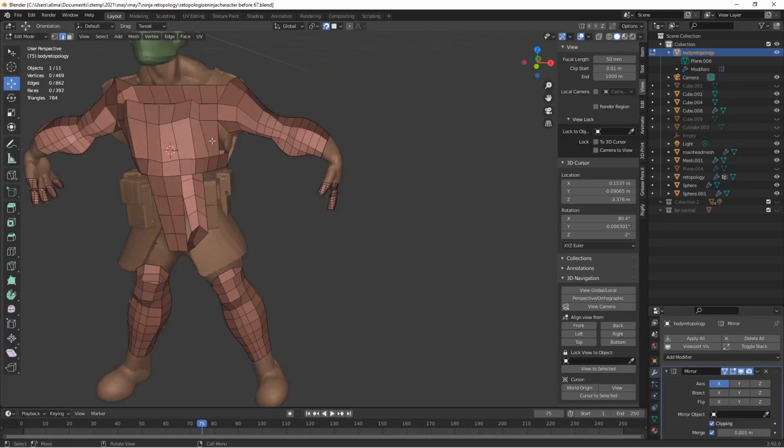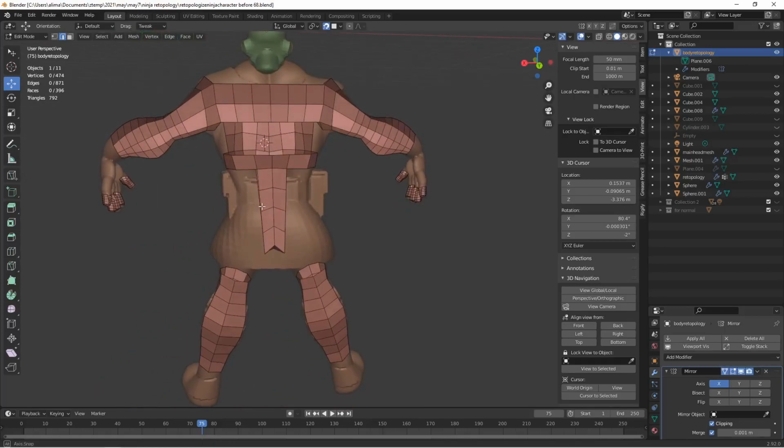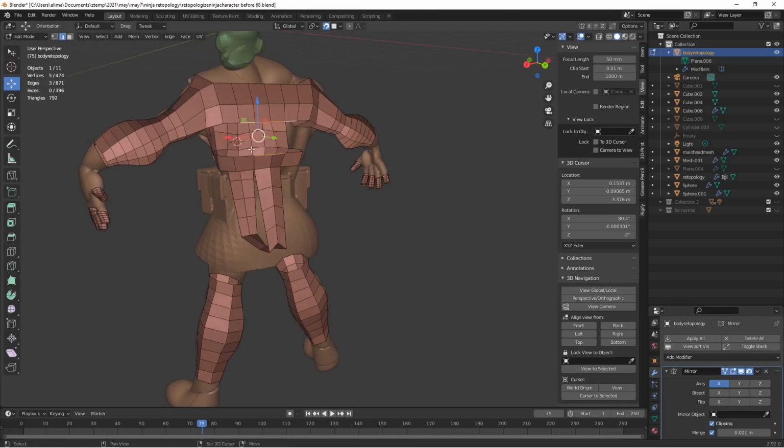I'm going to zoom in, hover here, hold Control, press R, left click once, left click a second time to lock in, left click on nothingness to deselect. I'm going to hold the mouse button, take a look here. Well, not just to take a look, we're going to connect this. So we're going to select here, hold Shift, hold the mouse button, rotate. We'll select here, as well as here, as well as here, as well as not there.